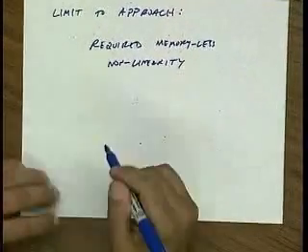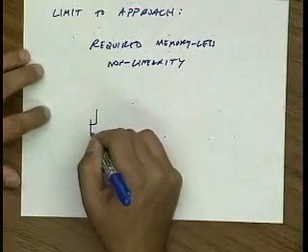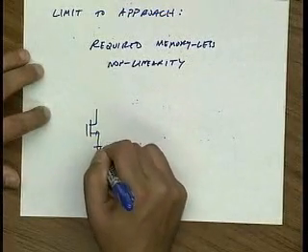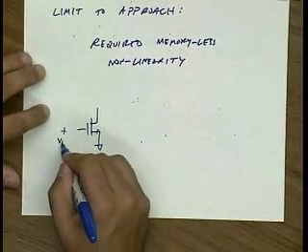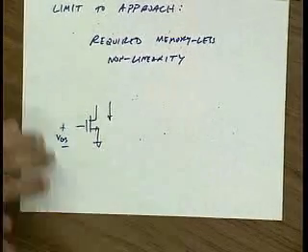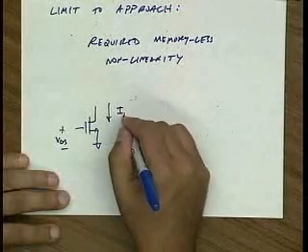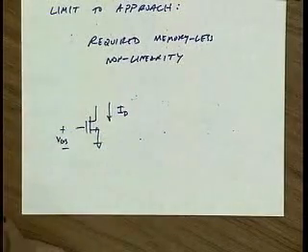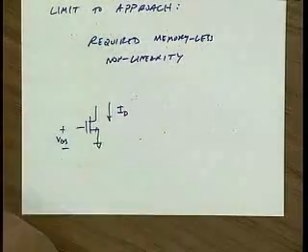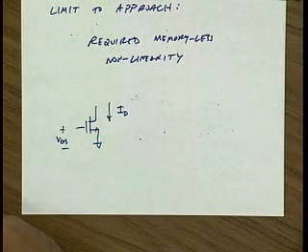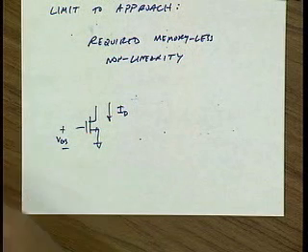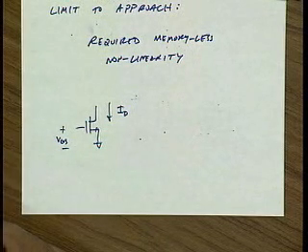Let's look at a transistor, right? Let me look at a FET and consider applying a large signal VGS here and what kind of current it generates. Now, what kind of elements inside this FET would generate distortion that has memory in it? Yeah, the capacitors, right? Everything else is memoryless.